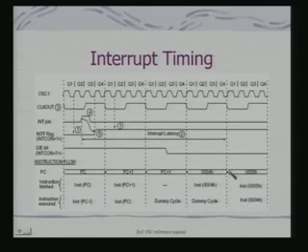After this, at this point you start execution of the instruction from that vector location and you fetch the instruction from the next location. So, this is basically the interrupt latency, that is a delay behind the servicing. The time gap between the interrupt occurrence and the service which can be provided.